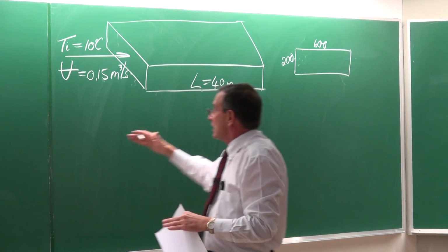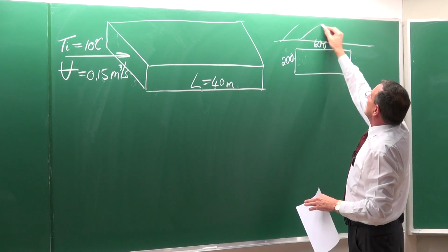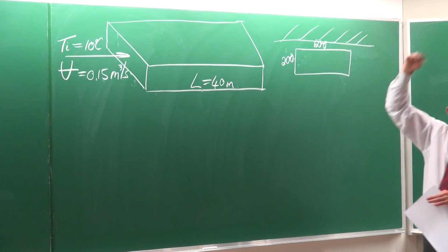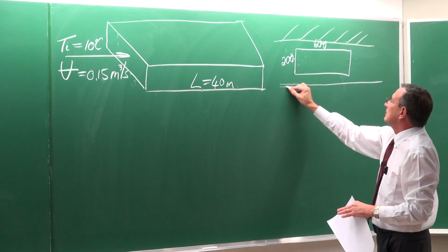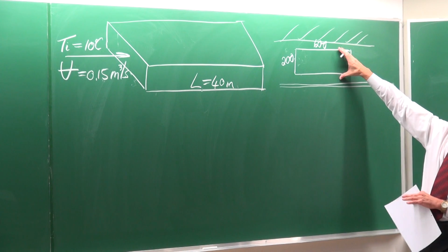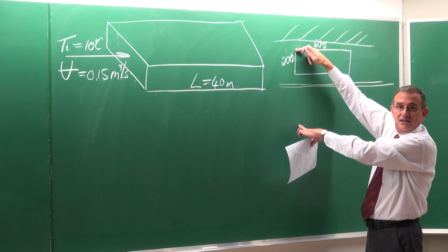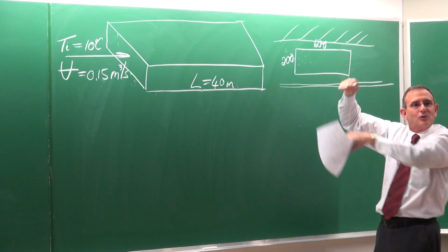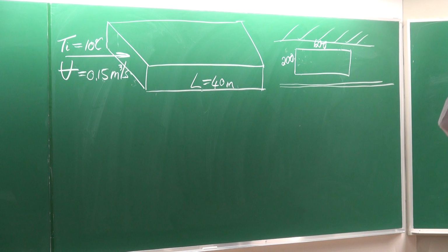To put the air conditioning ducts in there, if that is maybe the wall there or the floor of the next level, then they put in a false ceiling in here, like that, and then the air conditioning duct will be there. So normally it will not be 600 in this direction and 200 in that direction, because then you do not use that 600 millimeters of space.